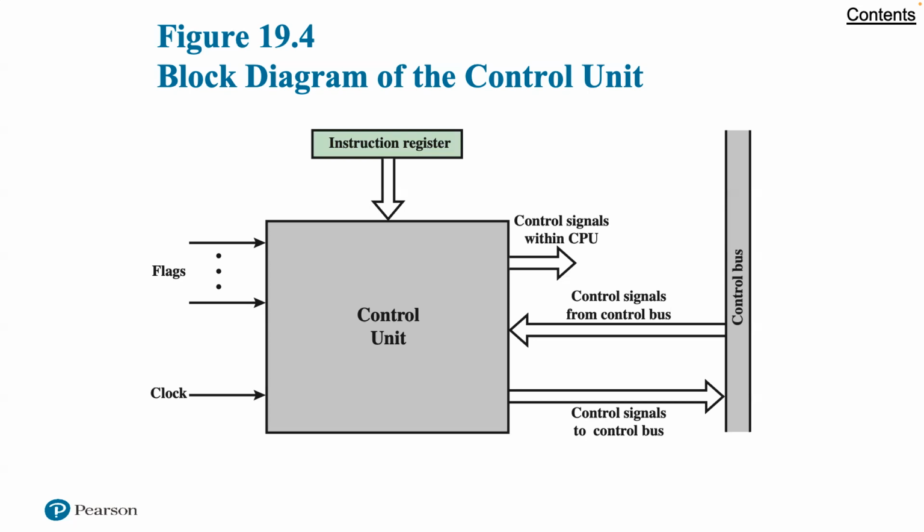This completes the fetch cycle, except for one thing. The control unit must decide whether to perform an indirect cycle or an execute cycle next. To decide this, it examines the IR to see if an indirect memory reference is made. The indirect and interrupt cycles work similarly. For the execute cycle, the control unit begins by examining the opcode and on the basis of that decides which sequence of micro operations to perform for the execute cycle.